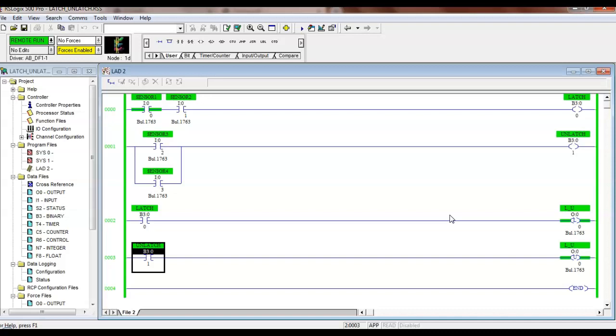You still have memory, you still have coils, so all of them have coils. Every PLC that you'll program supports ladder language. 90% of the program is going to be decision making. We don't want to sacrifice an output for a relay coil that's only in there to make a decision. Okay? So every one of them supports what we call internal relays. With internal relays, you do not sacrifice an output that does nothing. You understand what I'm saying?